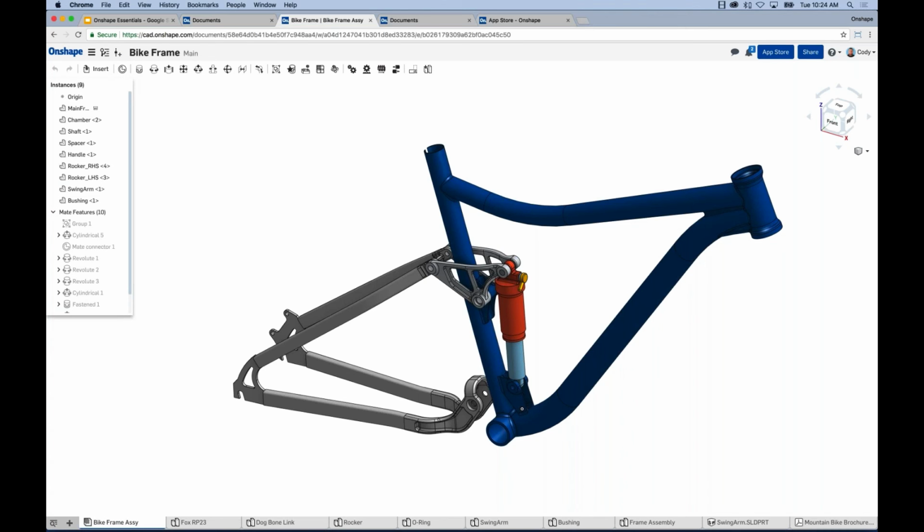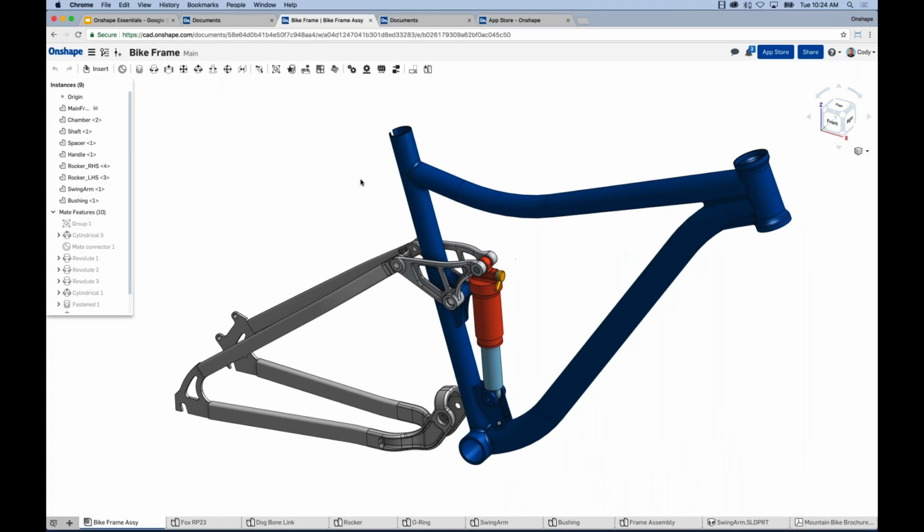Those are all in the Part Studio. If we go into a sketch, we would see sketch tools in this toolbar. You would see lines, rectangles, and so on. So just keep in mind the toolbar is always in the same place, right here at the top, but the icons, the things in it, will change depending on what you're doing at that time. Now, in this case, we're in an assembly, but we're going to jump into a part in just a bit, and you'll notice all of these icons will change.